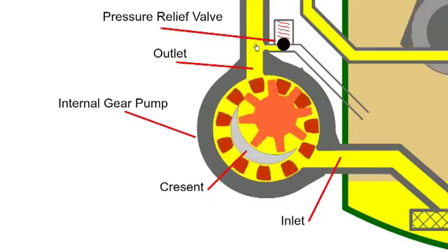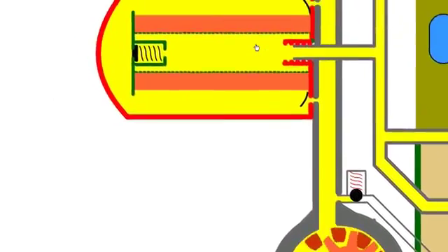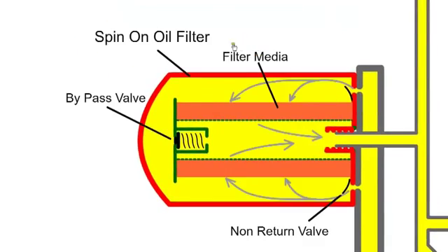As the oil lubricates the engine, it will pick up dirt particles which are removed by the filter. Early filters consisted of a housing and a replaceable cartridge filter. Later manufacturers introduced spin-on filters, which were easier to fit. However, recently the trend is back to cartridge filters, which are considered to be easier to dispose of. This is a spin-on filter. The housing and filter element must be changed as a unit.